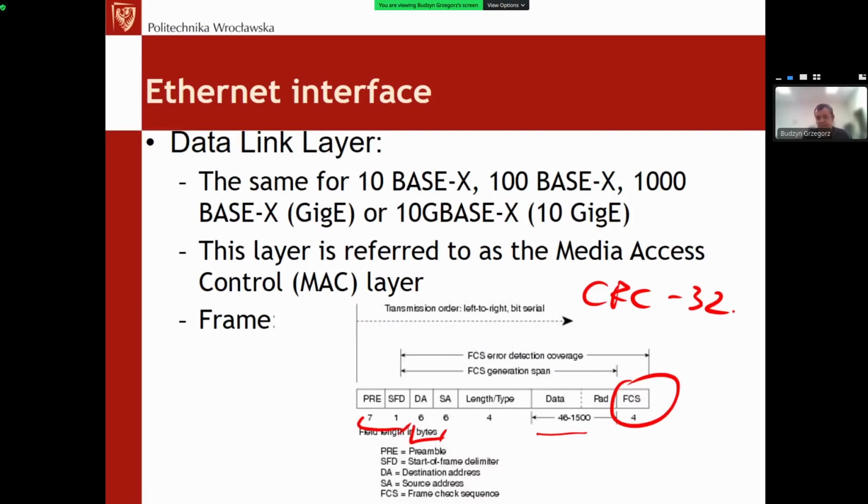This usually means that there is no sense of the Ethernet block in a microcontroller if a CRC peripheral is missing. Usually it means this, and besides, an Ethernet block is useless without a DMA. So if we can sum it up, if there is Ethernet, there must be a CRC and there must be a DMA available inside the microcontroller. Usually this is the case.